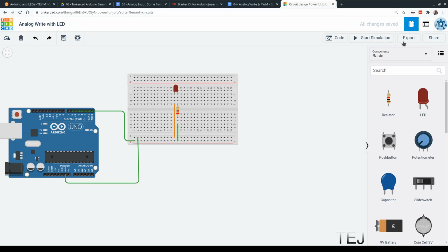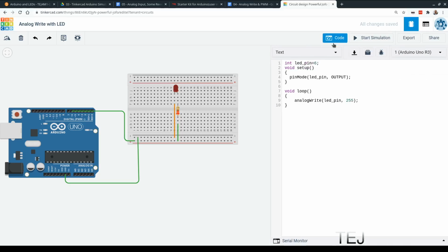So now when we look at our code and we start it, you can see that it shows 255 as the intensity. If I change this to, let's say, 120, you should notice that it's a bit dimmer. And it might be hard to see, but what if I put 50, then you'd probably really see it. And what if I did like 10? With the real LED, you would see it even more.